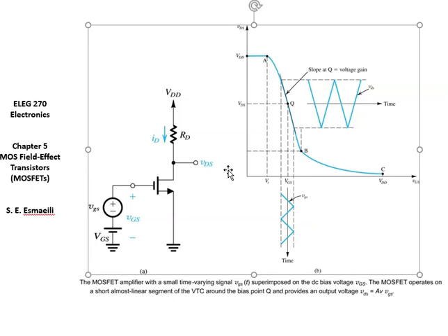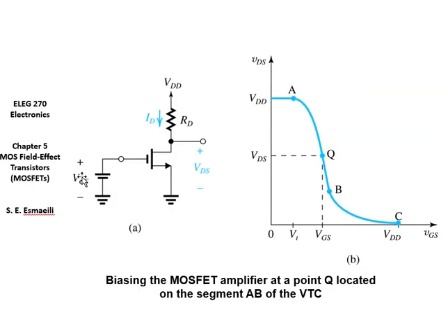The process is very similar to what we were doing with the BJT. There, we used to do the DC analysis, find IC and find gm, right? It's the same here. So first, you will forget about the AC source. You will imagine that it's not there. You will imagine it's like this. There's just a DC source. So you will do your normal DC analysis, and you will find ID.